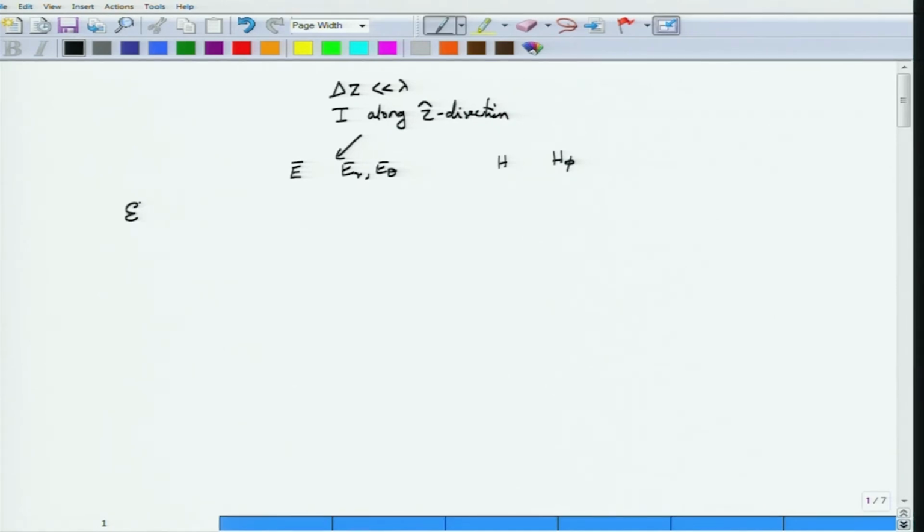So, first was the electrostatic region. In the electrostatic zone, the electric fields would go as 1 over r cube, and these fields would resemble the fields of a short dipole. You have two charges of opposite sign and equal magnitude, and the fields for the electrostatic region around the short wire antenna or the short dipole antenna would be equivalent to the dipole field.